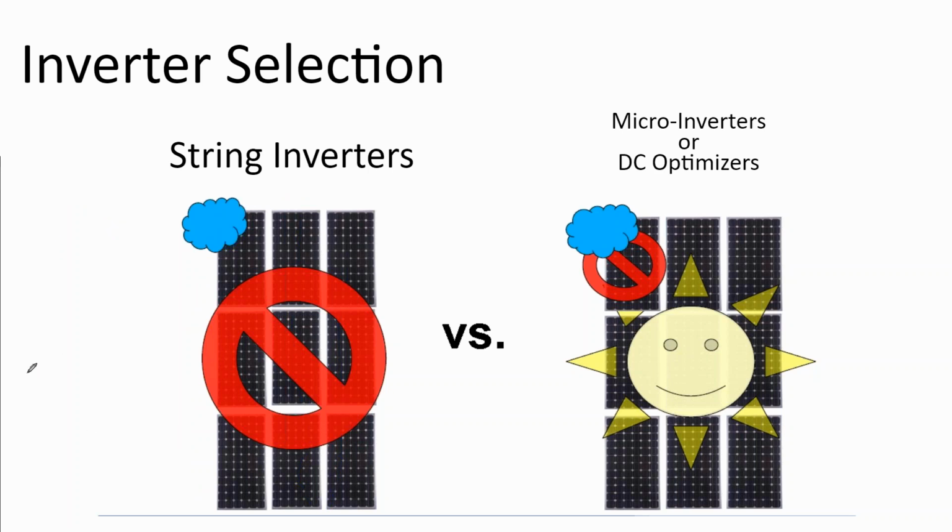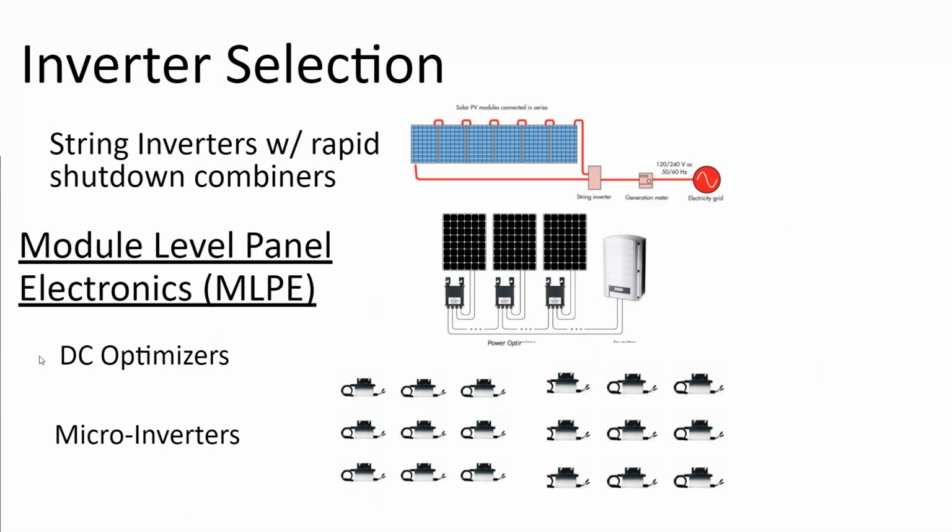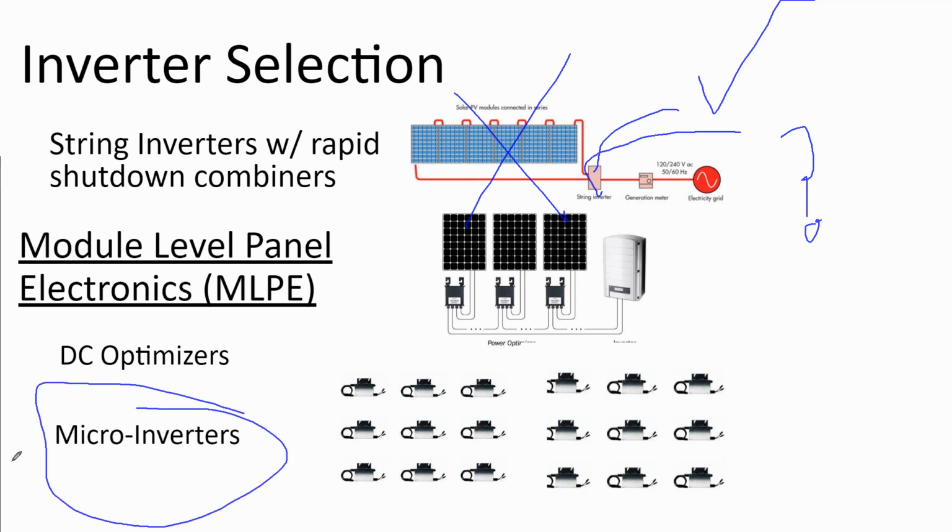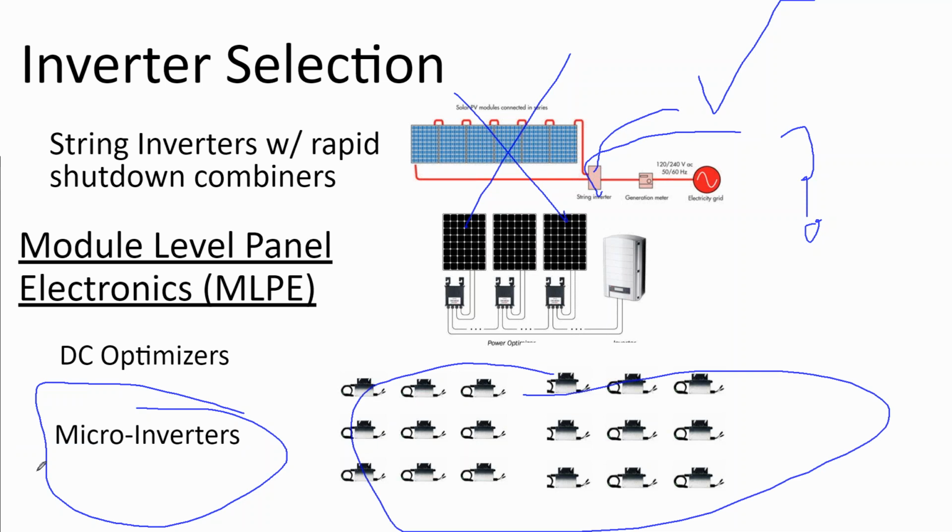And so a little bit of shade would impact that whole circuit, but the problem is when you have multiple circuits going into the one string inverter, and now some of the circuits are turning off and other circuits are turning on, the string inverter gets confused and says, look, voltage is jumping all around, I'm turning off until this is settled. And so clouds passing over the arrays would turn the arrays off beyond just the impact of the shade on the circuit or on the string. And so the companies that make microinverters said, we're going to invent a shade tolerant system.